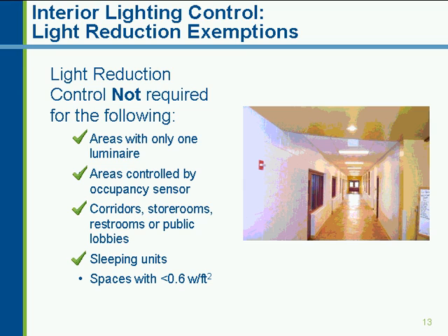Sleeping units, of course, are exempted, again, for practicality reasons, and also spaces with low installed wattage, less than 0.6 watts per square foot. Again, from a practical standpoint, that isn't as much energy savings, and therefore it's exempted.